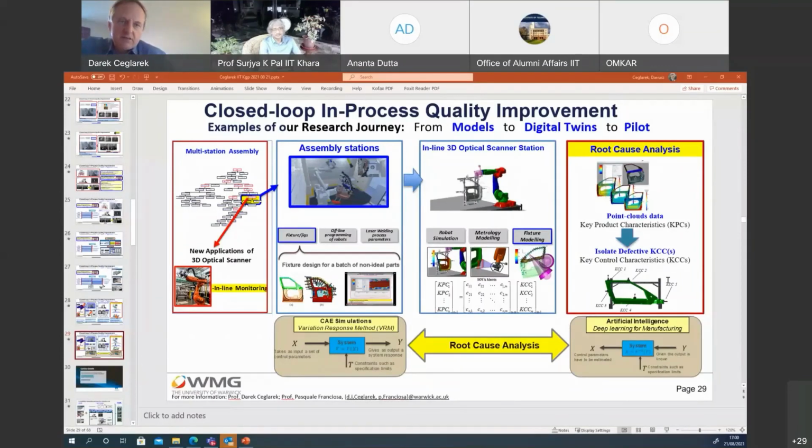For example, if I don't know anything about past production, because everything is quite different, then we use tolerancing, assume specific ranges, and simulate the parts, generating parts with errors. If we know from historically similar parts made before, and we know the variation, we include this variation in the simulator as well. This is just an example of uncertainty.